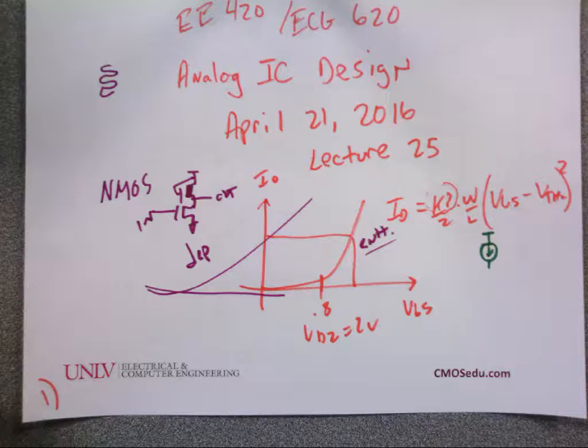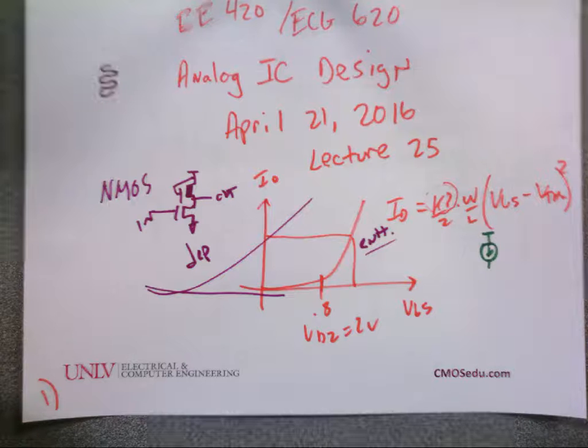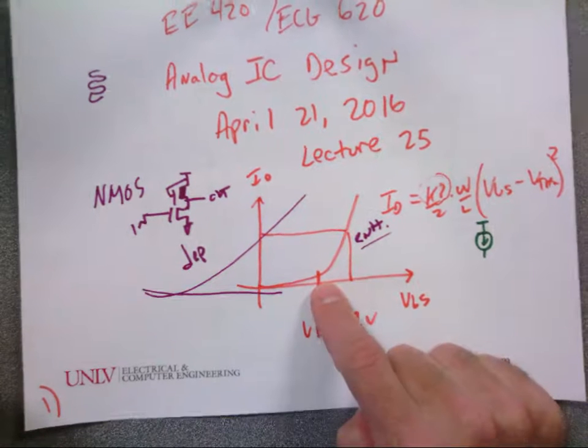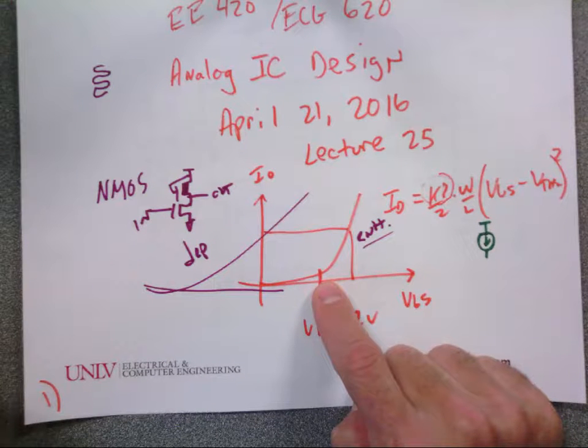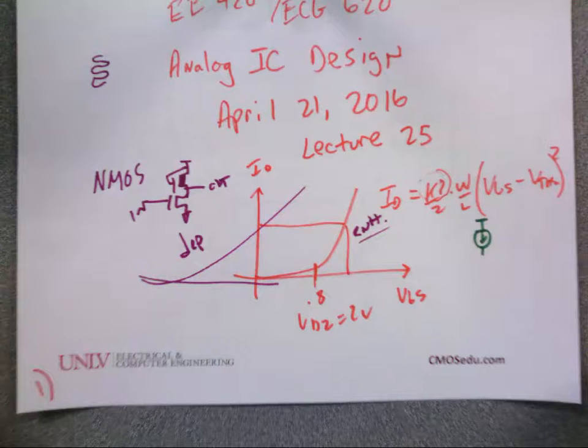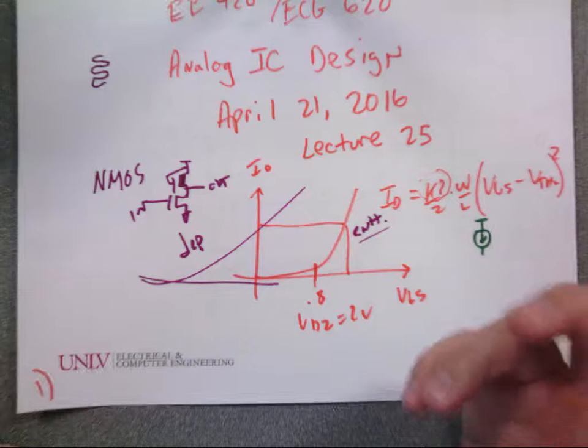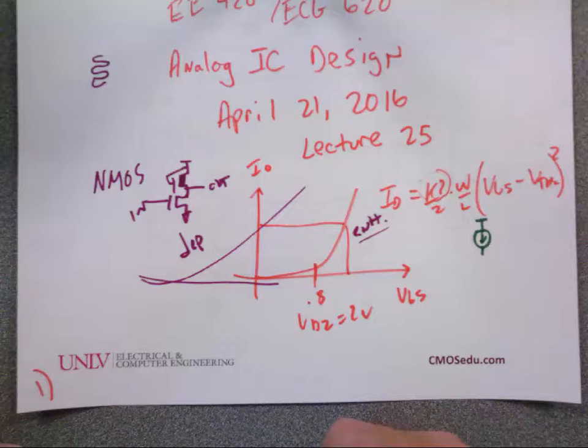Okay? So when you ask what's VT0, you can get a good approximation looking at the model, because there's a VT0, right? Yeah, it's a negative PMOS. But if you want to see what it actually is, you do the plots. When you go work in industry and they say, here's your models, they also give you a design manual with all the plots already in it from measured data. They take those measured data plots, and that's how they generate the SPICE model. So you design from the plots.